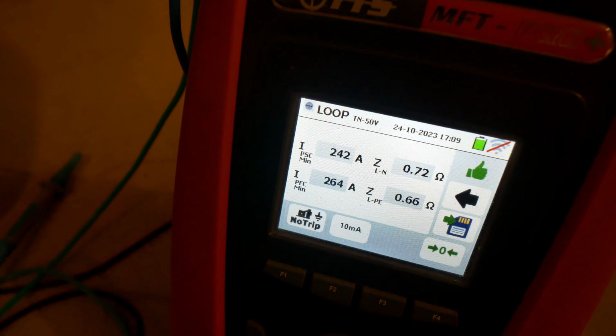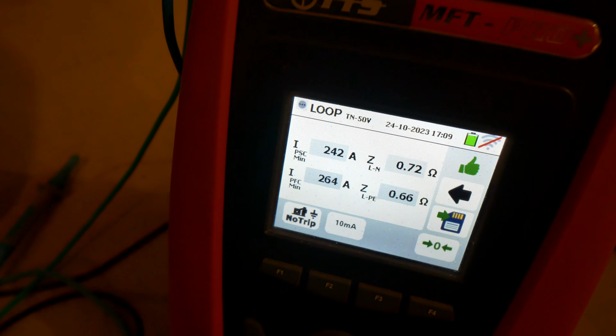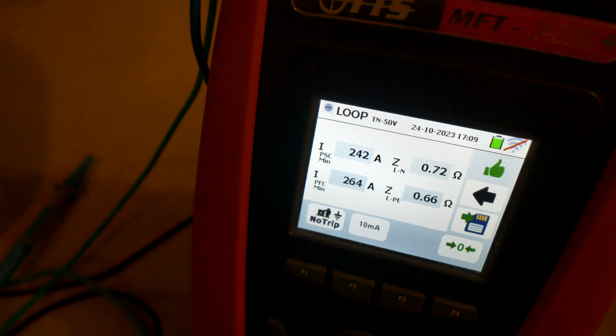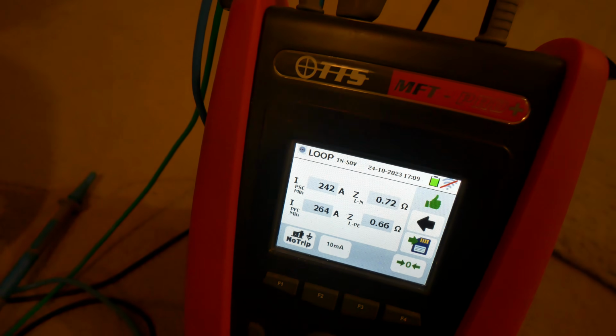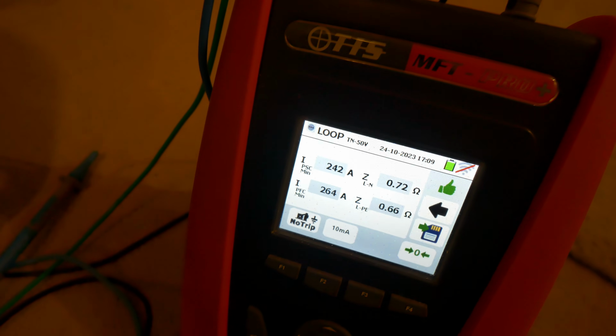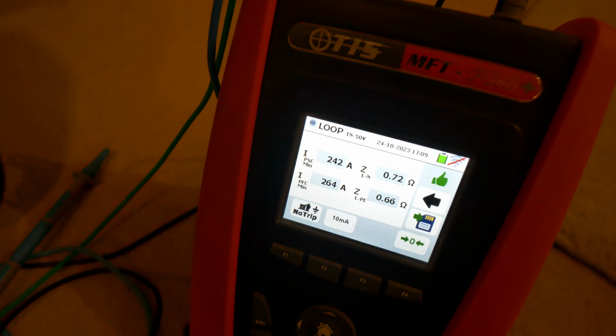However, I've got the test lights mates, so I'm going to pop them into the local light point and we'll see how that value compares to the fan. Having taken a measurement between the line supply to the fan, it should be consistent-ish with what we would get at that point as well. So just a bit of extra information. I'm not going to open the fan back up with it live and then try and take a measurement in there as well.